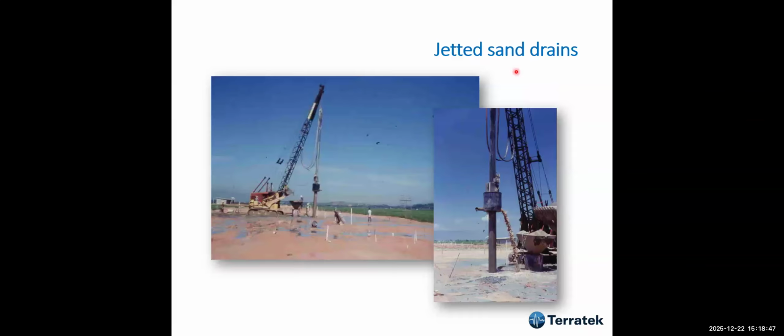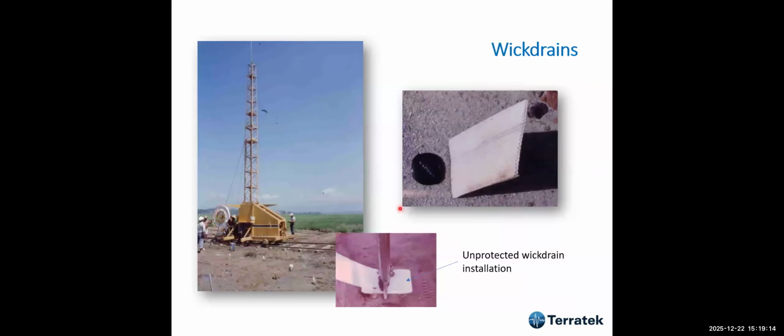Then there was another technique which was being used by a company on many roads in South America, the jet sand drain, in which they installed the drain with a water jet, and then the clay would be cleaned out, and they filled it up with sand before extracting the jet. And wick drains were a very new technique, brought to us by a Japanese company which made this kind of drain.